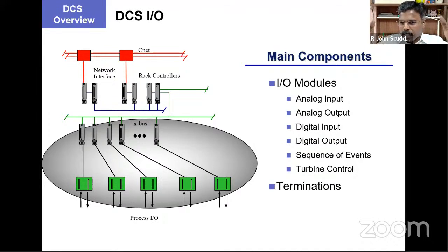In case you have this sequence of events recorder, it's very easy to analyze, and very interesting also, which event happened first, followed by which event, and if there is any logical time delay which has been already set, whether those things happened exactly as we had intended. Everything is easily possible to be analyzed. So this is one more feature of DCS which is very, very unique. And as I told you, there are so many other features which I'll be explaining as we go forward.